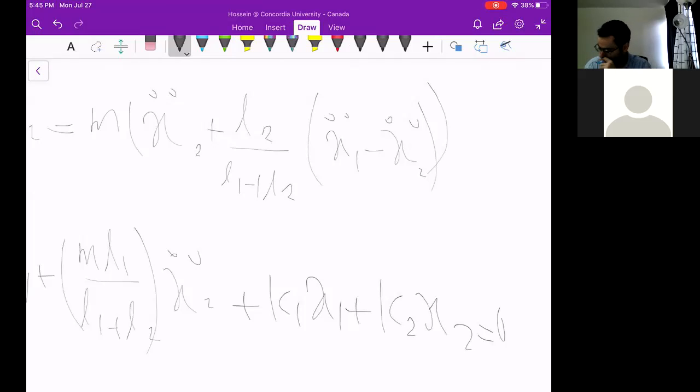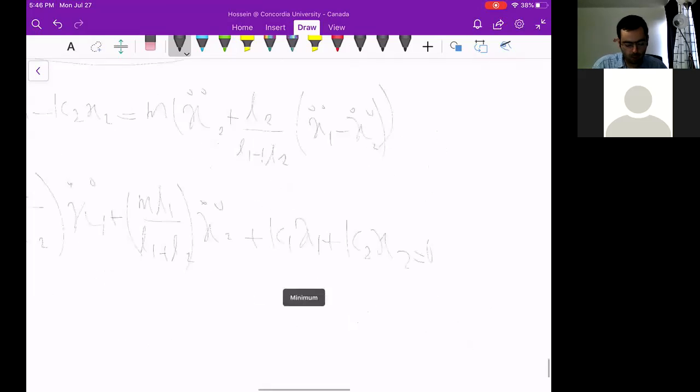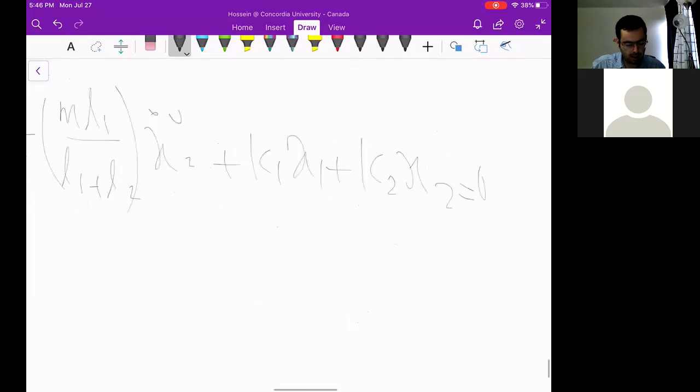and it describes the linear motion. However, we are only asked to determine the type of coupling that this system introduces. If you take a look here, since we have both x1 and x2 in one of the equations, in one row of the matrix format, this is only one equation of motion for linear motion, right? So in one equation, I can see x1 and x2. That's why I could say there is a coupling between x1 and x2.